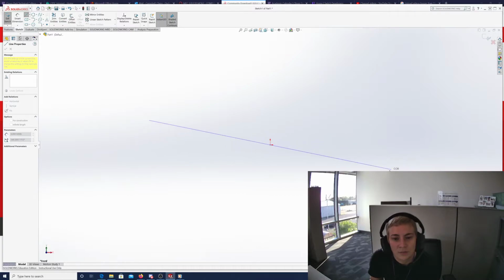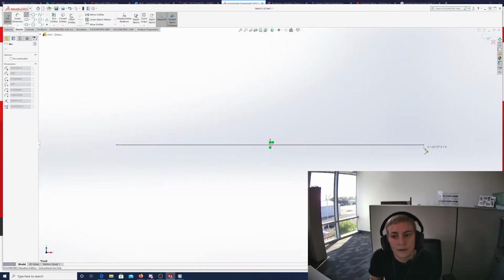So you can make your line however you want. You drag your mouse around. So let's just do a horizontal line right now, and do that second click, and that's going to pin the end of your line. Then after you've done that, it's going to let you continue a line, or if you hover back over that endpoint, it'll make an arc. So you can see I've got different kinds of arcs going here.